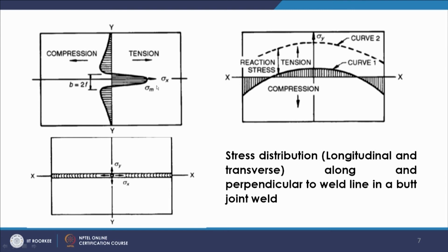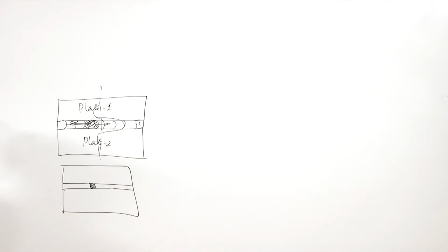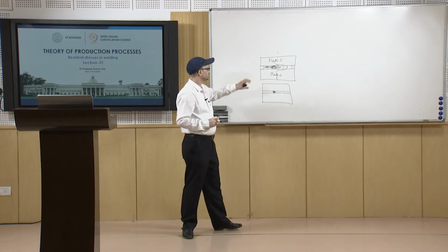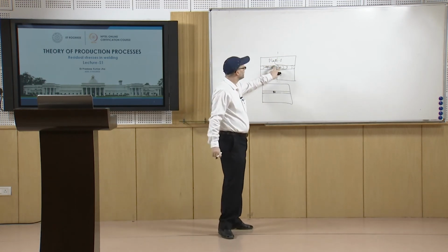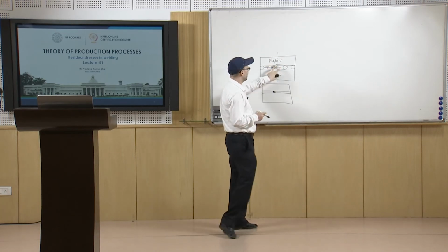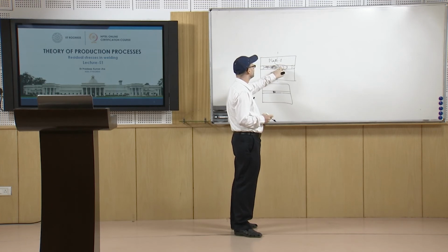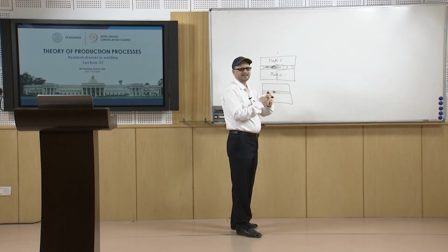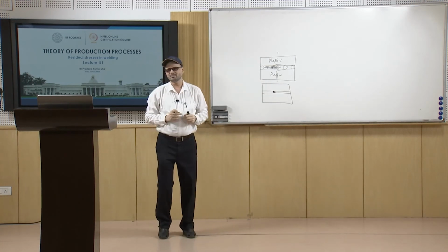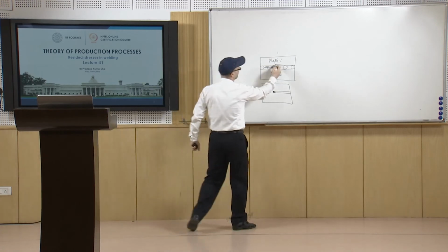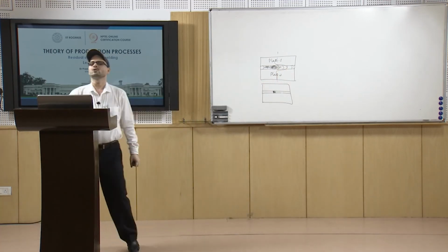That is what is seen in the middle portion when we are talking about the longitudinal side, looking at this section. In that section, this portion is subjected to compressive stress, because in the end it tries to remain in the expanded state, and this is trying to contract it. So, this leads to development of a compressive type of stress in this region. Similarly, this region tries to get contracted, and these two regions try to pull it. So, a tensile type of stress is developed in this zone, and that is how it goes.